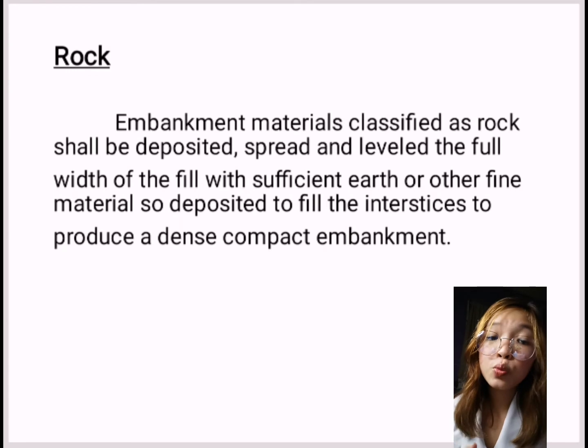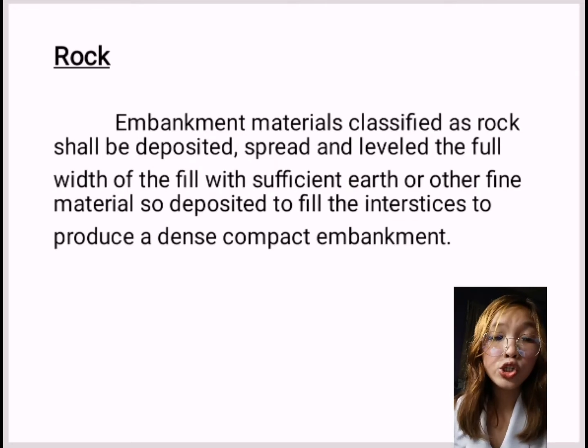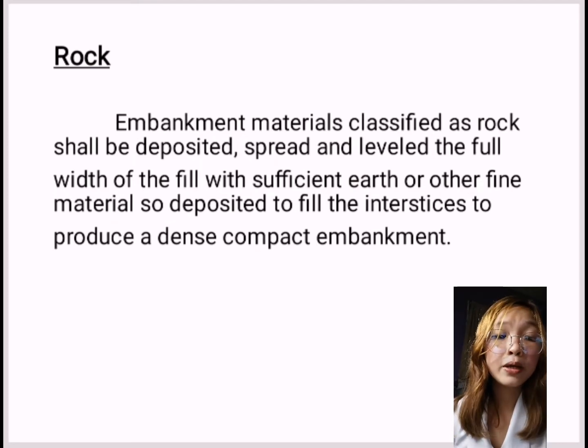So in addition to this, one of the rollers, vibrators, or compactors meeting the requirements set forth in subsection 106.2.1, or the compaction equipment, shall compact the embankment full width with a minimum of 3 complete passes for each layer of embankment.